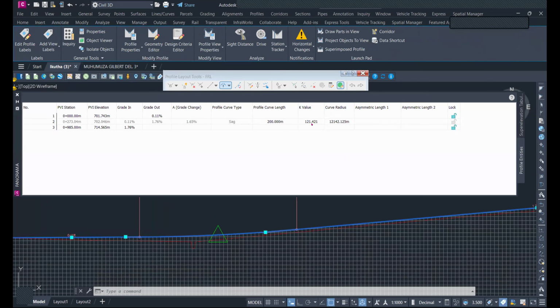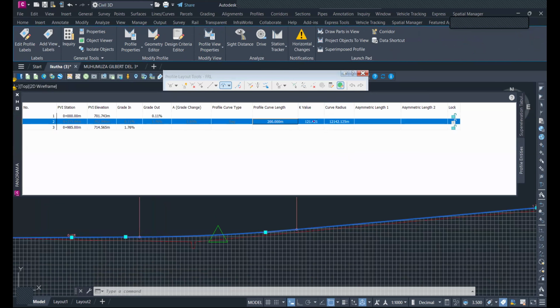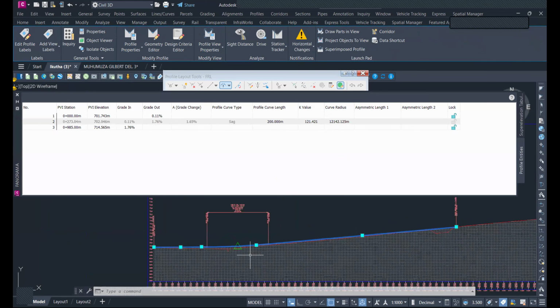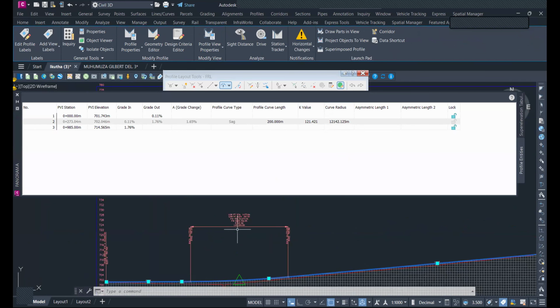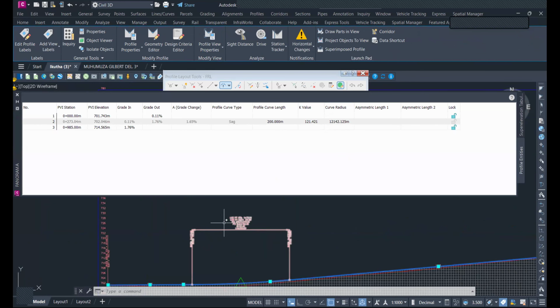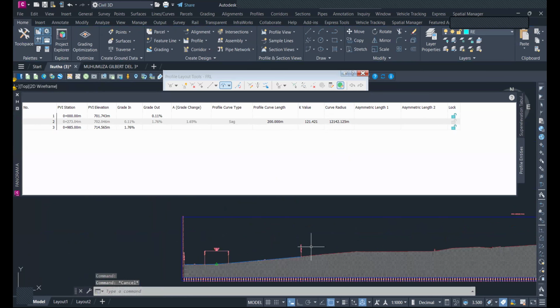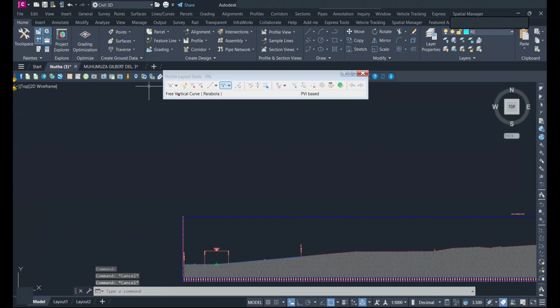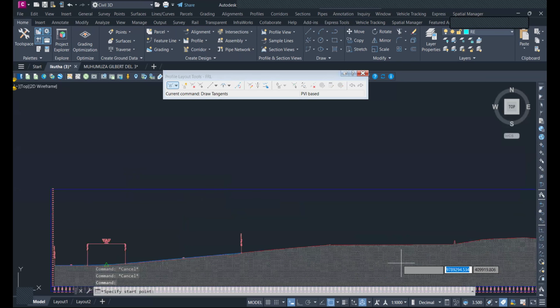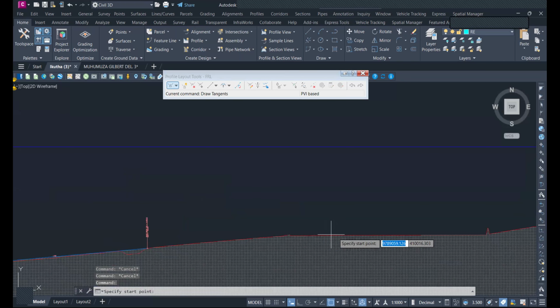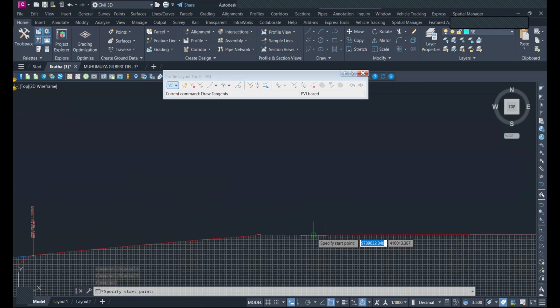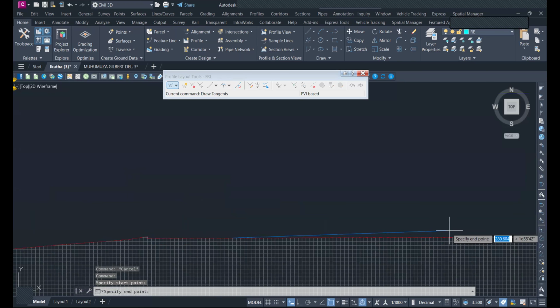If you can see the K value, once you give the curve length, it populates the K value naturally for you. The bigger the K value, the more gentle the slope or the curve here, and then that looks great. You're going to be doing the same thing even for this other side. You gauge that and you know that your straight section will be probably somewhere up to here, and you're done.